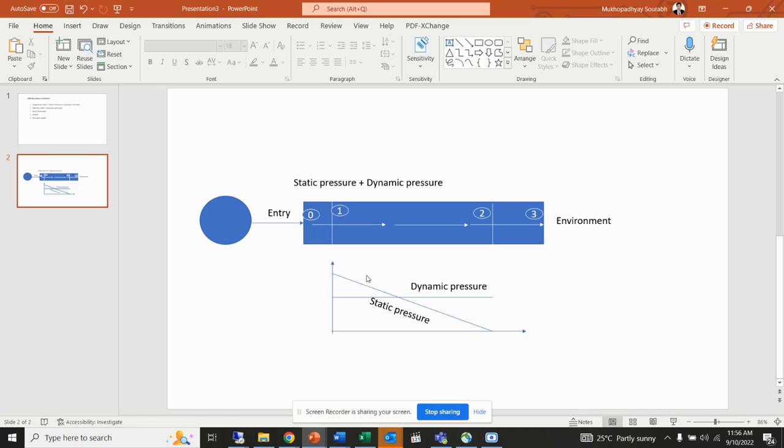And the static pressure remains dependent on the downstream resistance. And after that, once the total pressure is defined, the code auto calculates the static pressure from the system resistance, and it subtracts the system resistance from the total pressure.